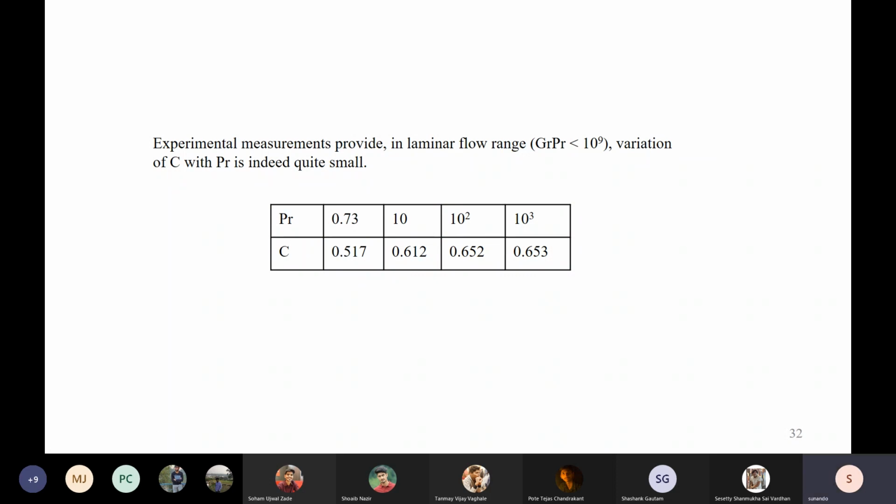So what you get then, therefore, is a relation for natural convection that you have obtained without going through a complete solution, just based on your physical understanding of the system. And this is what I am trying to tell you time and again, that transport phenomena should let you think about the physics of the problem, which would allow you to arrive at solutions which may not require involved math in order to get the final solution.